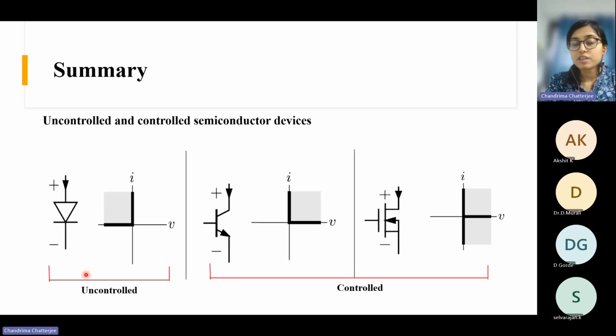And next up, we have this. We studied in detail diode, right? Which is an uncontrolled device. We studied the static characteristic of the diode and also the dynamic characteristic of the diode. What is the dynamic characteristic? The dynamic characteristic of any switch means the voltage, current, all this information with respect to time. Right, the waveforms. Those are the dynamic waveforms.